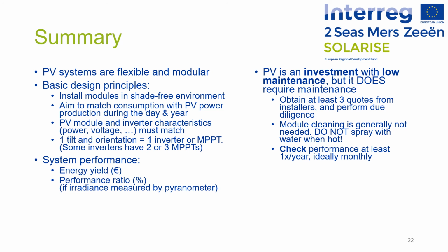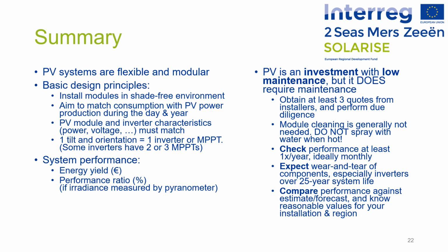You need to check the performance at least once per year and ideally monthly. You also need to expect wear and tear of your components, especially inverters, over a 25-year system life. You also need to compare the performance against the estimate or the forecast and know reasonable values for your installation and your region.